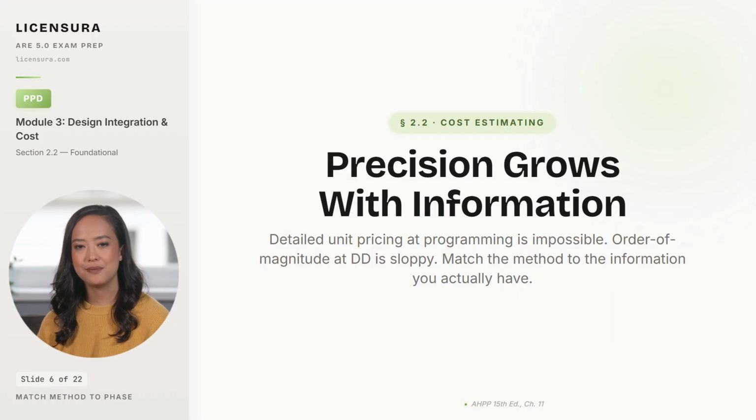Here's the cost estimating mistake most architects make at least once in their career, and the exam loves to test it: applying the wrong estimating method at the wrong phase of design. You cannot do a detailed unit cost estimate in programming because there is nothing to measure, and you have no business using an order of magnitude square foot estimate at design development, because by then you have enough detail to do real assemblies-based work. And sloppy estimating at DD is how you launch CDs quietly over budget.